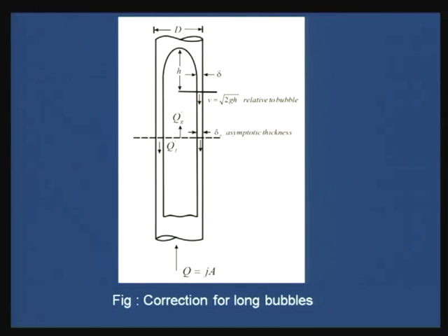Now, we know that if you observe this, again we find that in this particular film region, by the same logic, the wall shear, or there is no particular pressure drop here, isn't it? This entire portion can be assumed to be a region of constant pressure, as I have already discussed. This does not contribute to the pressure gradient. You agree with me?